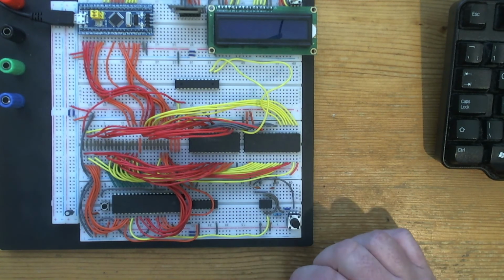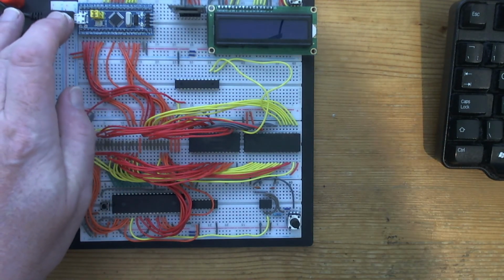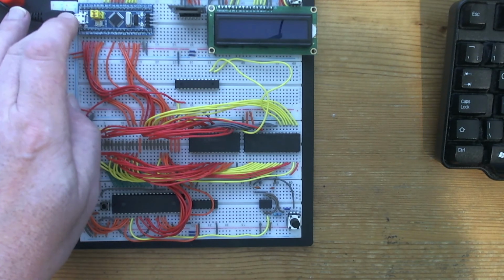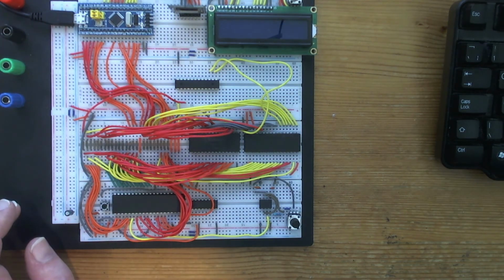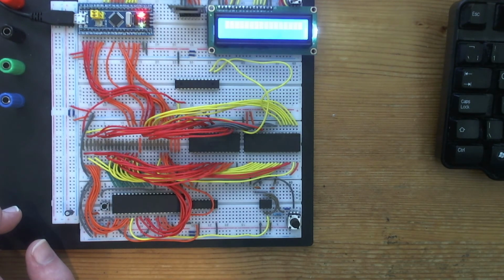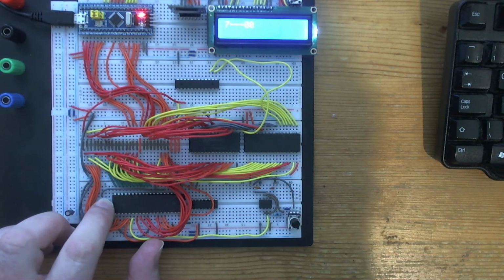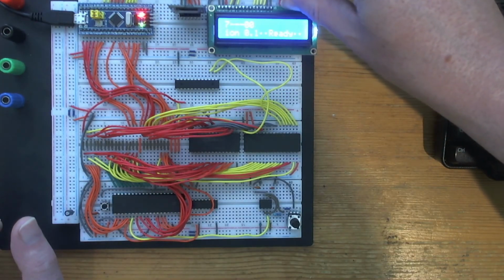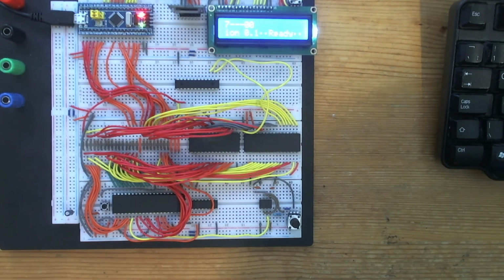I continue to use the BSX. So we've got the USB plugged in over here to the blue pill STM32. This is actually providing power for the board as well as some I/O. So I'm going to plug that into my computer now. There we go. I haven't got a proper reset circuit in here, so I'm going to hold the reset. There you go. You can just about see, if I adjust the brightness, we've got something on the screen there. So let's see what's happening on PuTTY.